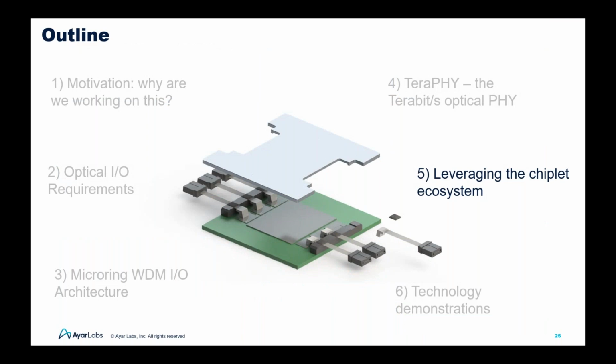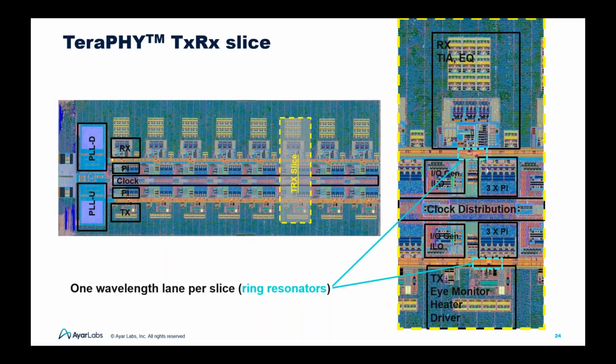So, just another question on that. Each of the micro rings has 8 lambdas, and there's 8 of them, so that's 64. Do I understand that correctly? No, for each lambda, you need 1 micro ring. Actually, you need 3: 2 for receiver, 1 for transmitter. One of the receivers is dummy; you can ignore it. When I point to the three here, this is one pair of the TX and RX, and we have 80 of the TX and RX. Each of them is going to have 3 ring resonators. 80, yeah. 10 macros.